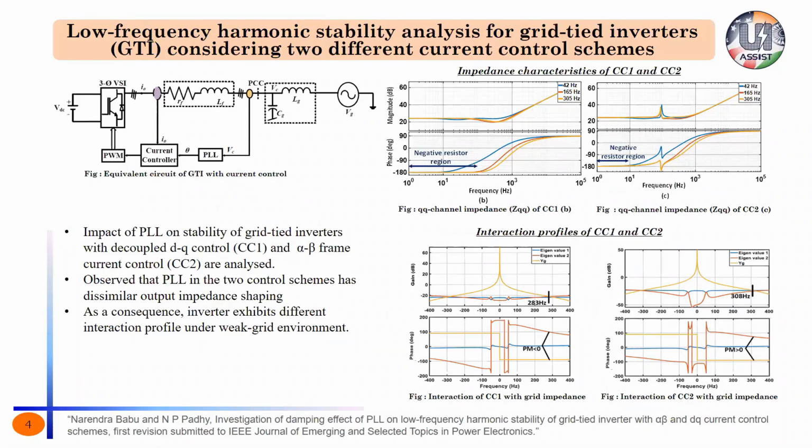Because of the presence of grid impedance, what we call a weak grid, there will be coupling among these inverters. Because of this coupling, the dynamics of one inverter will always have an impact on the performance of the other inverters. This we call inverter-inverter interactions. We visualize these kinds of interactions as impedance interactions.